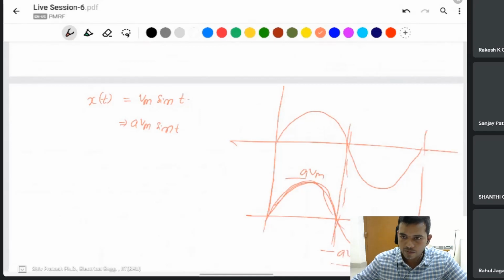No, sir, what I'm asking is, if the original waveform for which we need to find the Fourier series has DC, and we downshift it to have 0 DC, then find the Fourier series and arrive at a final result, how do we compensate for that downshift in the final result? How much you downshift, that is the DC value, so that we need to add.